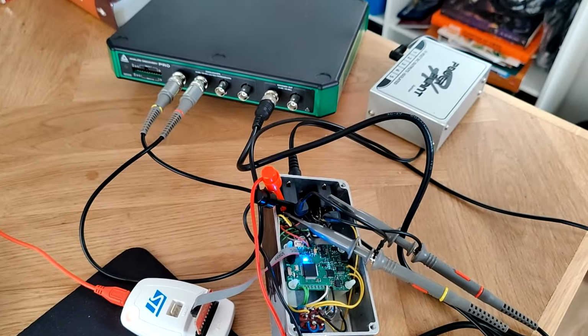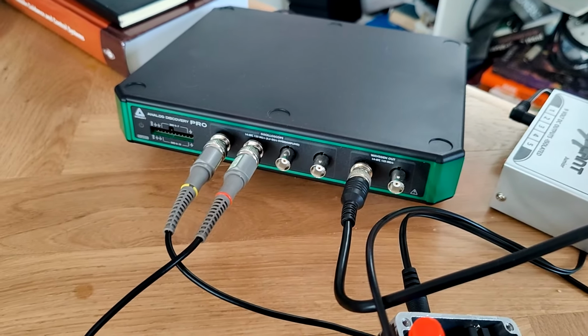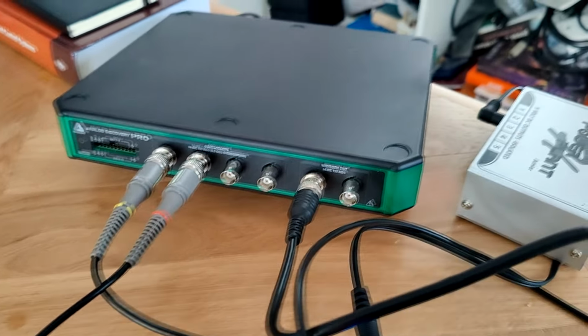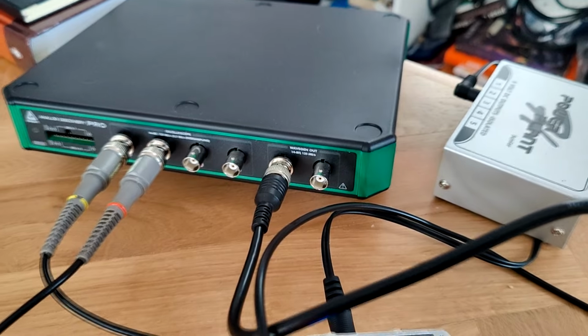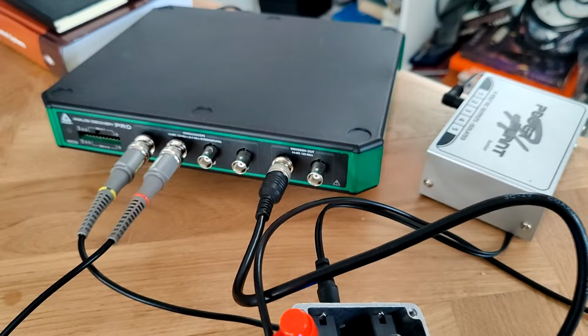So this is the setup that this is running on. I have my Digilent Analog Discovery Pro. I have 2 oscilloscope channels, one to measure my input to the system and one to measure the output of my system. And I have this one signal from the WaveGen out connected as a function generator to test my system and perform some analysis.